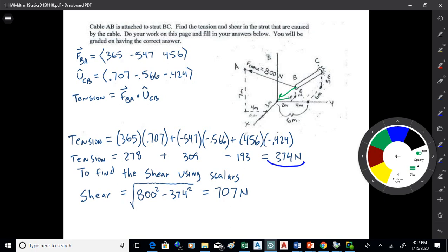Okay. Is shear always positive? What's that? Is shear always positive? Yes. Because I notice it seems like if you get a negative answer, you're just going the wrong direction of shear anyways. Yes. So the shear is inherently positive. Generally speaking, in statics, when you get a negative answer, it simply means you assumed the wrong direction and you just need to turn your assumption around. That's really all that means. It's usually not a big deal at all. It just means turn it around.